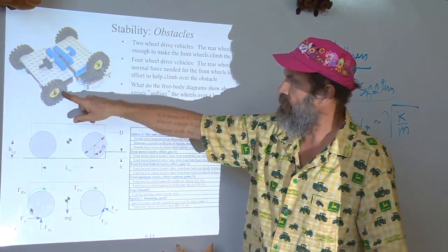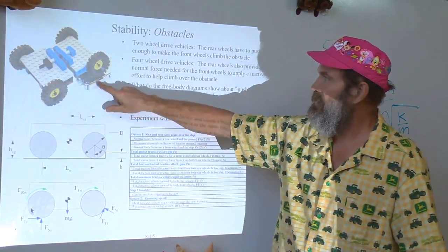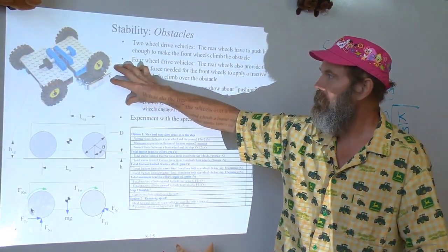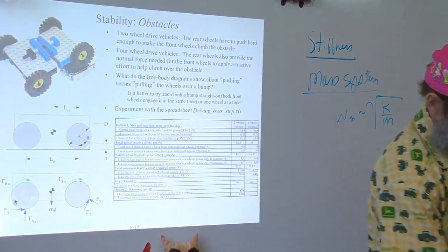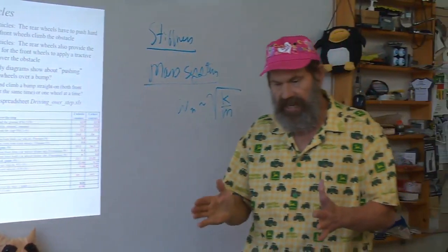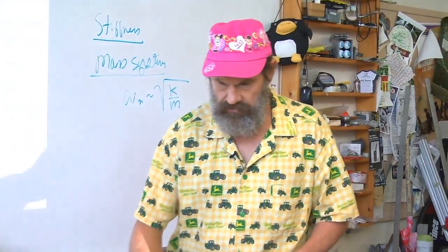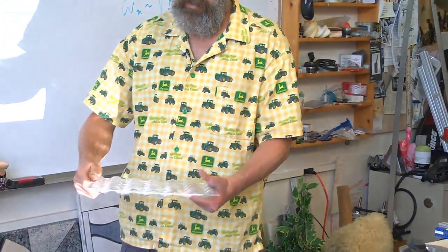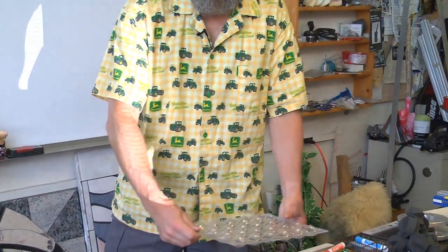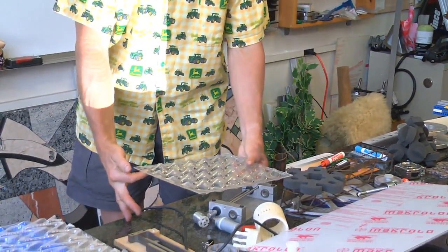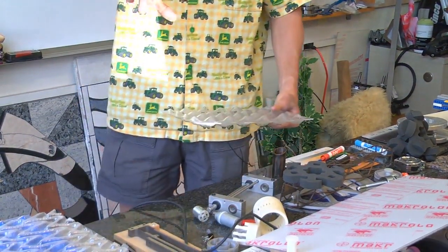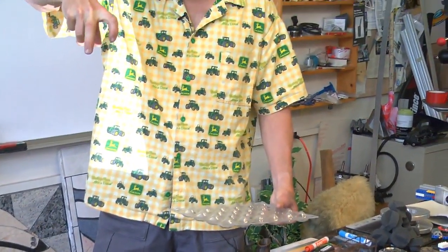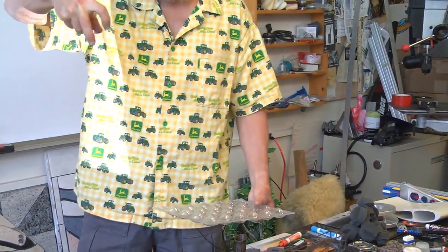For example, if this is a four-wheel vehicle and one tire has to go over a big rock, if the chassis was just a plate with four wheels on the corners, as I'm driving along I would come into a condition where one wheel goes high, and the machine would now be like a four-legged stool with one leg short, and the structure would rock, and it would be unstable.